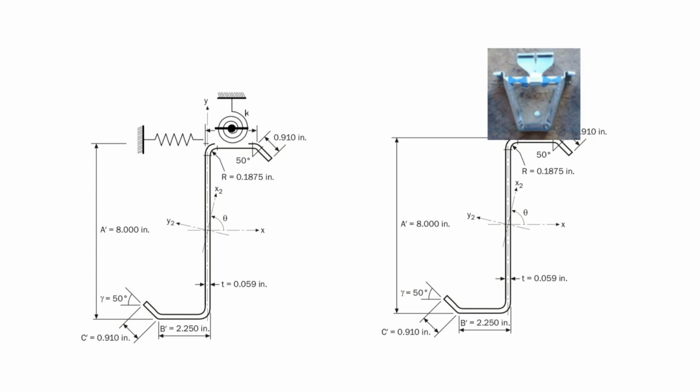The clip is screwed to the top flange. What we're trying to do is calculate the demand loads on the purlin, and also consider, on the capacity side, the influence of this clip. For those of you who work in this industry, there are many different varieties, flavors, and heights of clips. There are tall clips, low clips, fixed clips, and sliding clips. So today we've set the example up to be pretty general, so that in the future we can include the stiffnesses associated with the specific clip that you're dealing with.